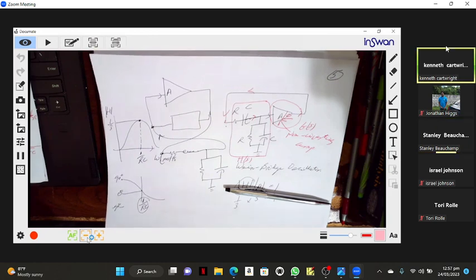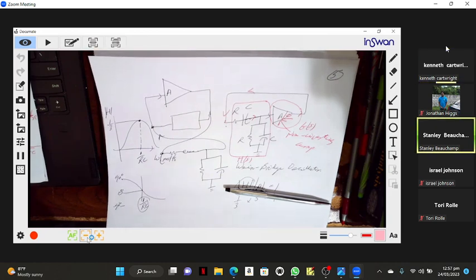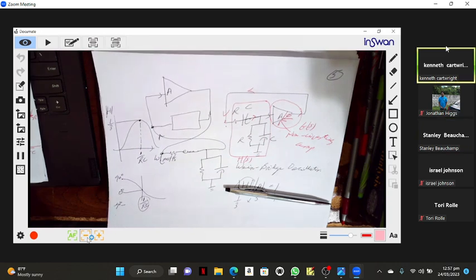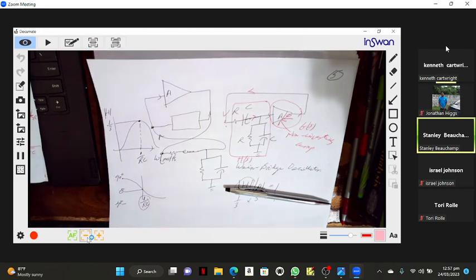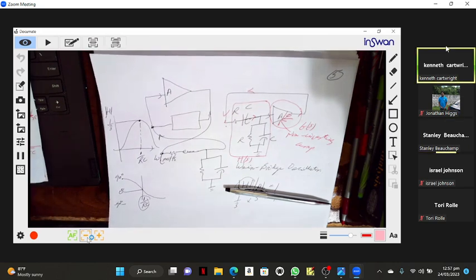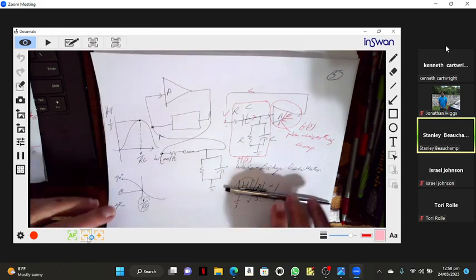I'm asking if the gain, you say non-inverting, right? Yes, and it's 1 plus RF over RI. So what did you say earlier? That's why I said earlier RF should be 2 times greater than RI. That's what they say, and you say nonsense. Well, that's why I'm checking again to see whether I heard you correctly the first time. Yeah, that was my statement: RF is 2 times greater than RI.